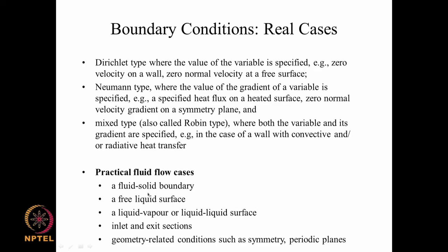So if you look at the three physical realistic boundary conditions, here you have a non-permeable rigid interface, and a free liquid surface, a liquid vapor or liquid gas interface, which is not rigid, but it can move, it can deform, and you bring in surface tension and normal stress balances and all that.